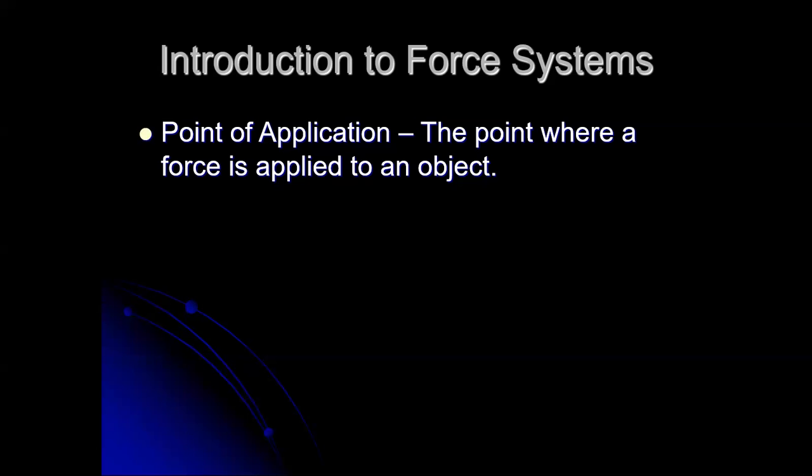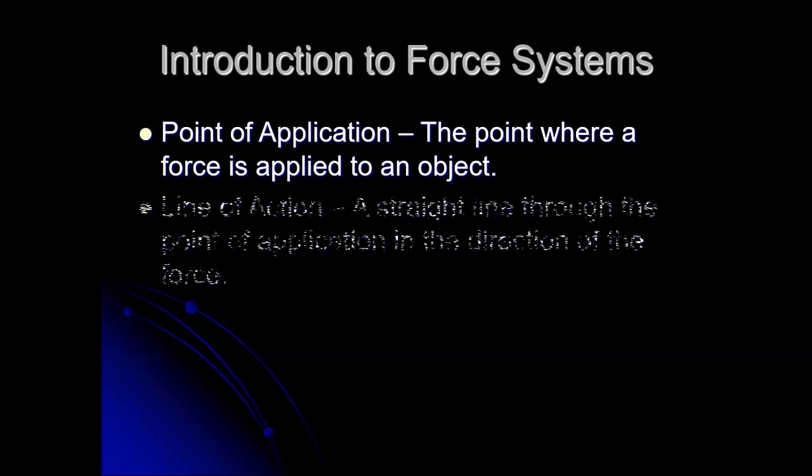We will look at distributed forces a little bit later. And the big goal there is to figure out how do we turn it into a point force, an equivalent point force. That's effectively what we do in weight and balance when we try to find the center of gravity of an aircraft. The weight is a distributed force. The center of gravity is the point of application of that weight force. It's where we can think of the weight as attaching to the object.